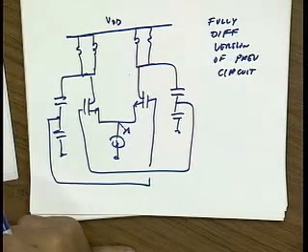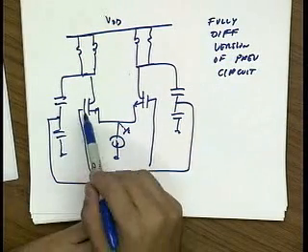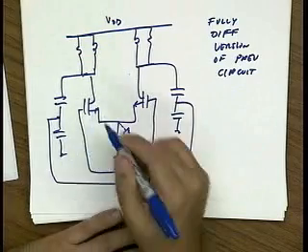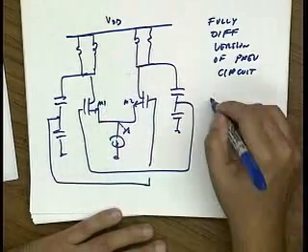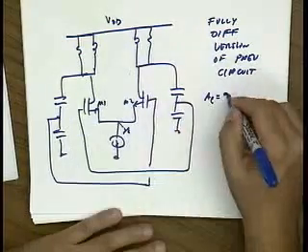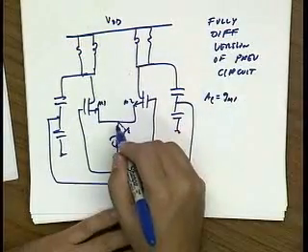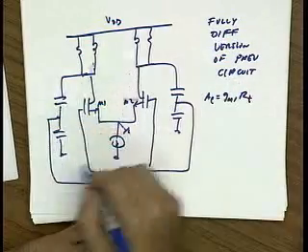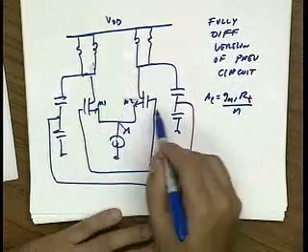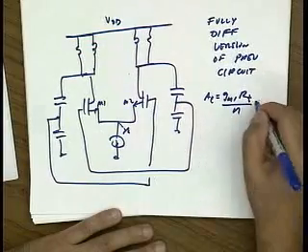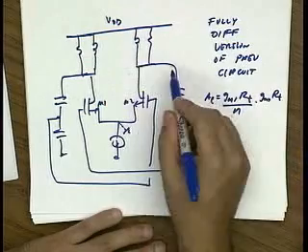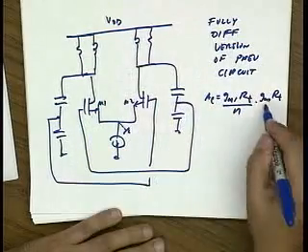Well, look at what happens to the loop gain. Now this device is not acting like a follower, it's acting like a GM stage. So the loop gain is GM1, this is a virtual ground, times this R tank divided by N. That gets applied here, multiplied by GM2, R tank, and then also divided by N, and the signal comes back.